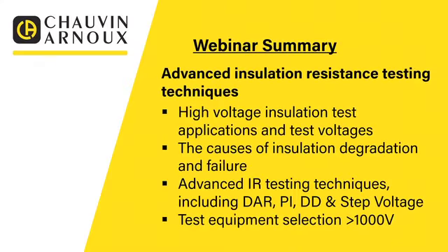So that brings us towards the end of the webinar now. So just in summary, we'll go back over what we talked about. This was talking about the advanced testing techniques that we can do with our insulation resistance testers. We started off with having a look at the actual applications and the test voltages used, and we looked at things like the discharge currents and the absorption currents and leakage currents.